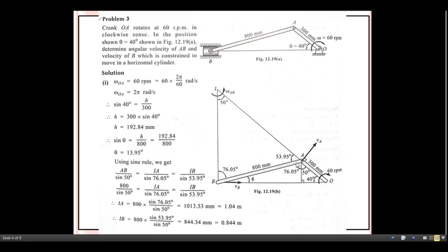So the VB component is here, and the VA component is here. Draw one line perpendicular to this VA component, extend this line at the back side, and extend the line from this point B towards the back side. The intersection of this line and this line occurs at this spot, so this is nothing but the instantaneous center I. Now what about the angle? Why do we need the angle here? Because my target is to get the values of the lengths IA and IB.